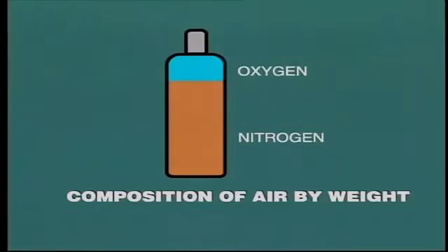And where do we get this oxygen? Well, a small amount may be contained in the fuel, but generally we derive the required oxygen from the air, which is all around us. Air is composed of oxygen and nitrogen in the approximate ratio by weight of oxygen 23% and nitrogen 77%. So in order to create the combustion reaction, all that is necessary then is to supply air to a combustible element, such as carbon, and ignite the mixture.